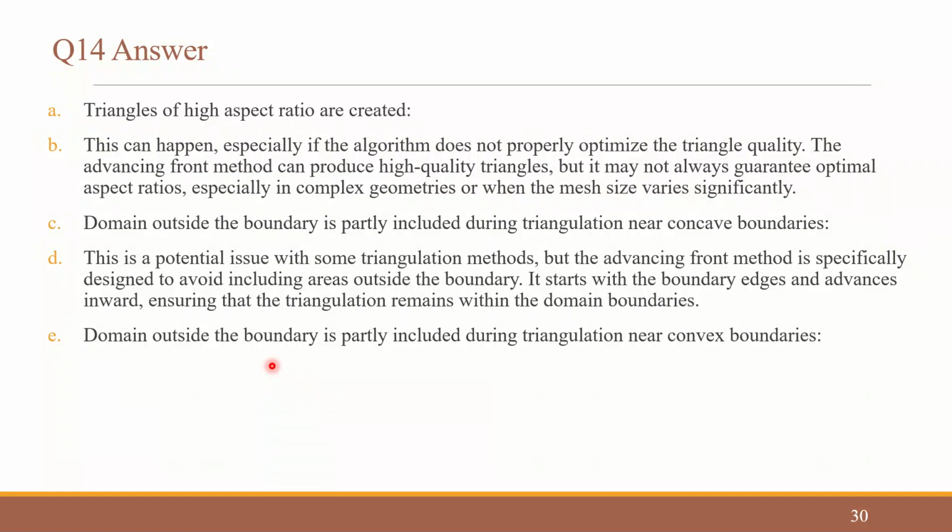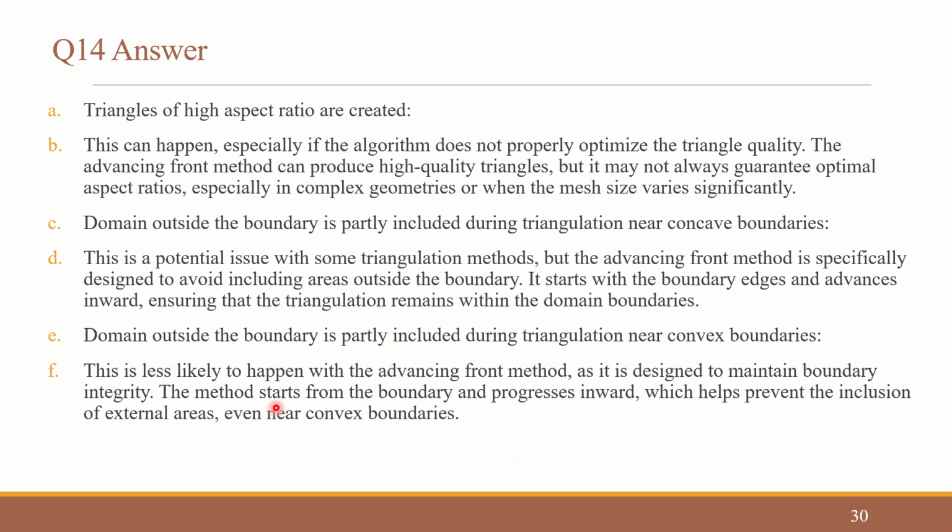Last one, domain outside the boundary is partly included during triangulation near convex boundaries. Again, it is false. This is less likely to happen with the advancing front method, as it is designed to maintain boundary integrity. This method starts from the boundary and progresses inward, which helps prevent the inclusion of external areas even near the convex boundaries. So that is with the advancing front method. We will go to question 15.